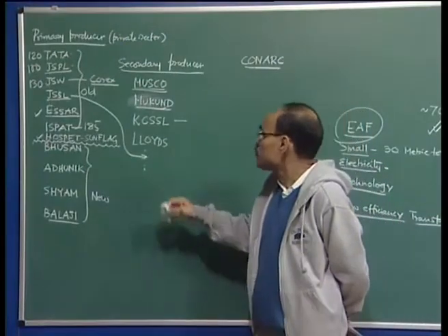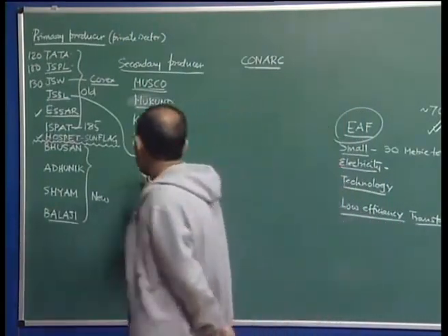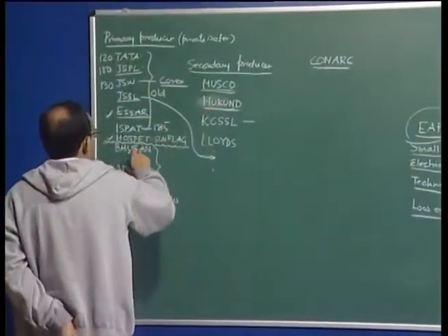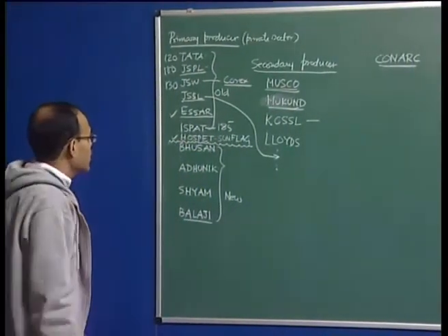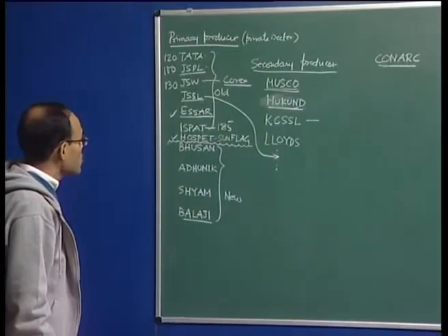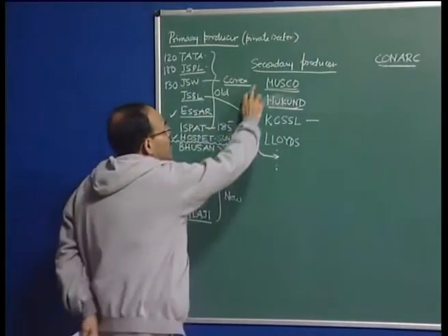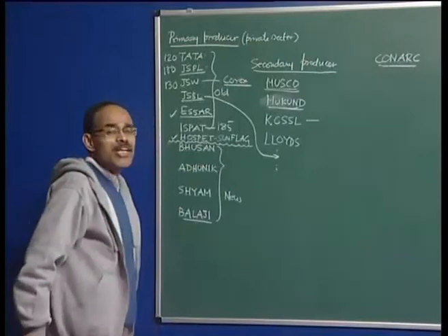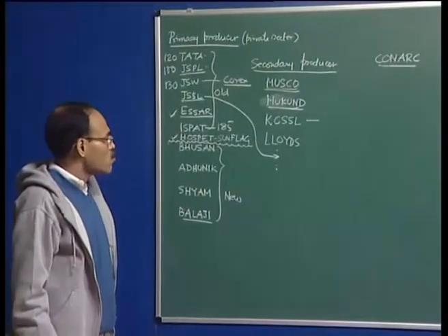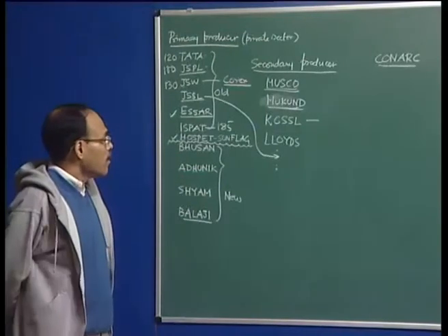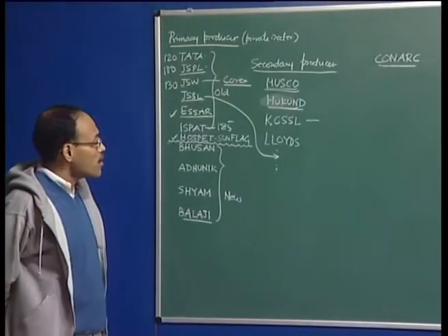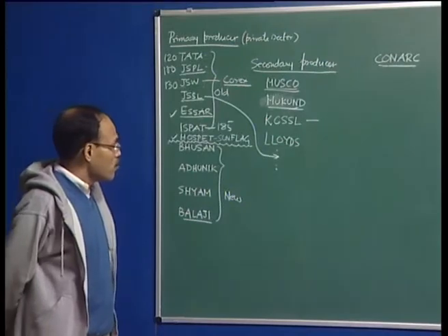Similarly, Hospet Steel also buys some DRI from some sources. These plants also buy scrap from the market, and they have huge scrap storage facilities, because it is the scrap mixed with the DRI that constitutes the principal iron bearing feed to the furnace.